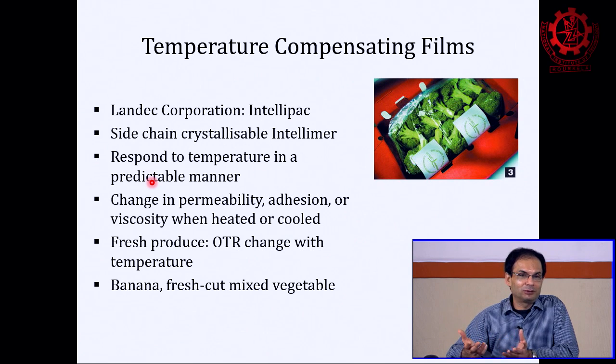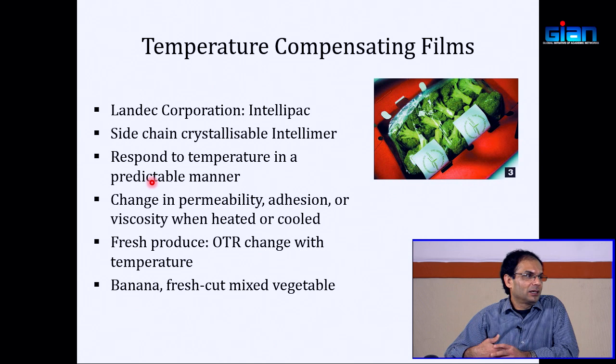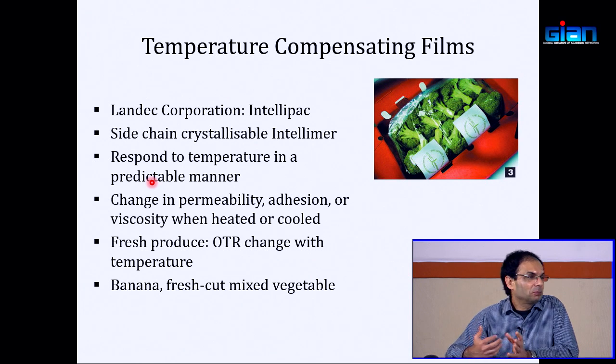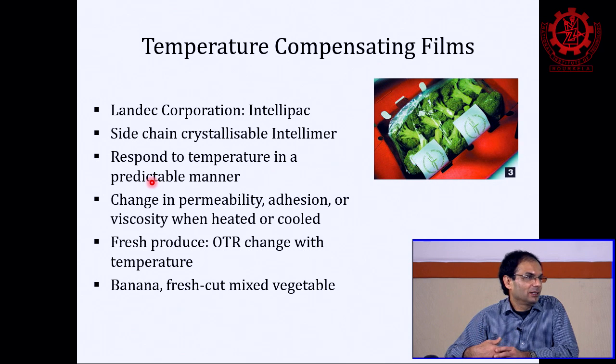Compared to if you have fruits and vegetables at room temperature, right? For example, you store at refrigeration temperature, and based on that, you have all the calculations of modified atmosphere packaging, you have a certain film. But what about during transport, during handling, when there's a temperature rise? If the temperature rise happens, then your respiration will change.